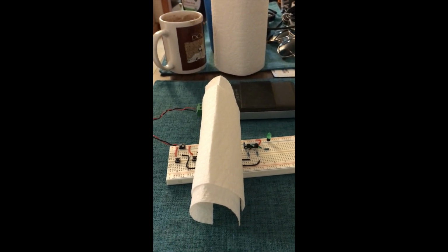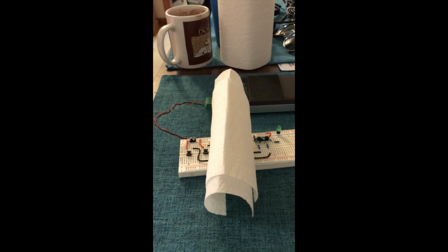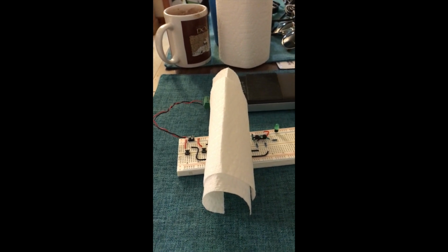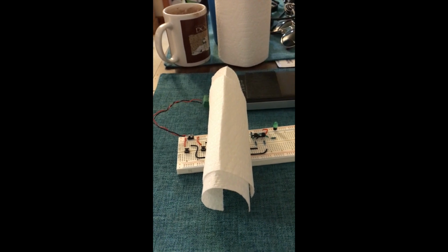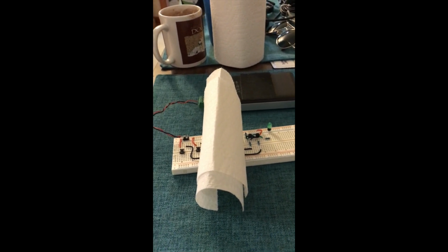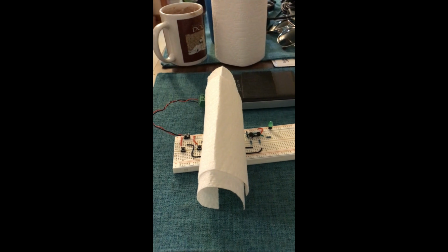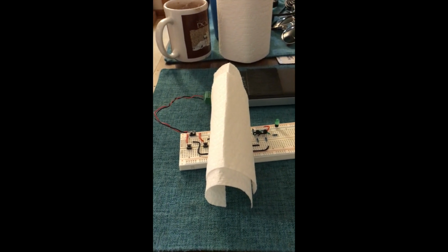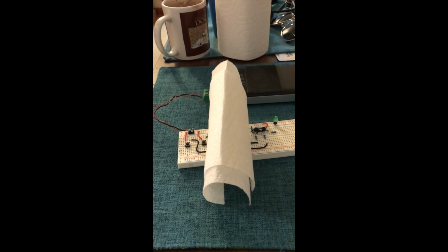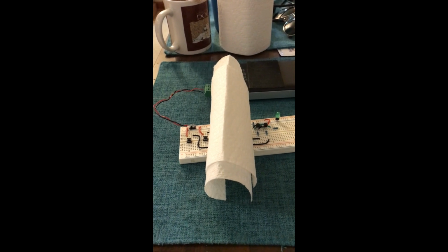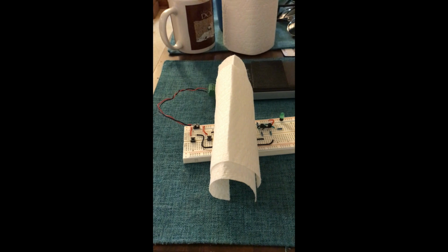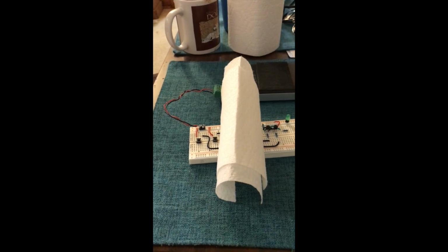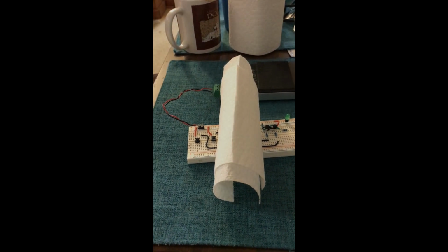So now we're in a position to think about using AND and OR gates to make a circuit that will detect any majority out of 3 voters. Any pair of them voting to turn the light on should turn the light on. Anything less than that, pushing any individual switch, should not turn it on. And again, pushing all 3 should turn on the light. So we'll have a go at that next.